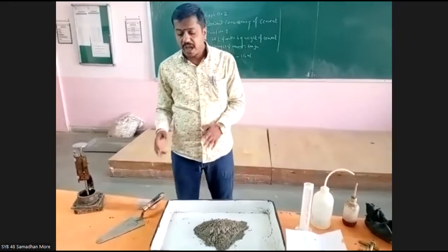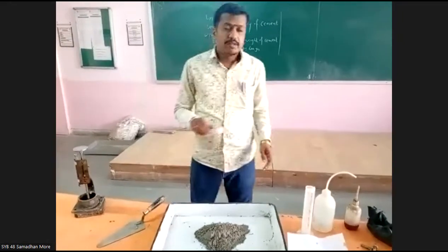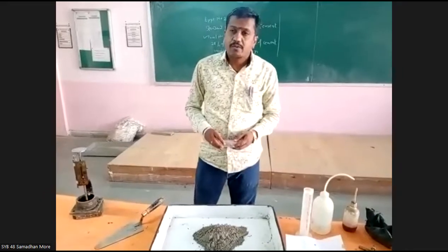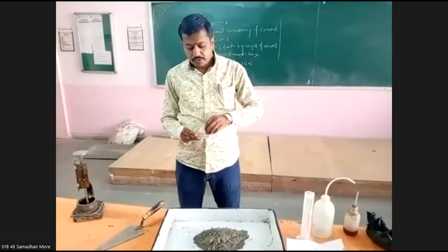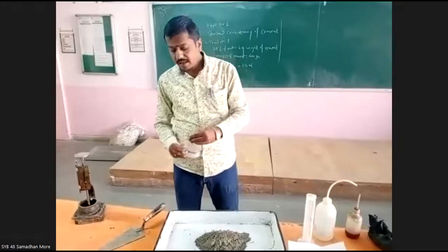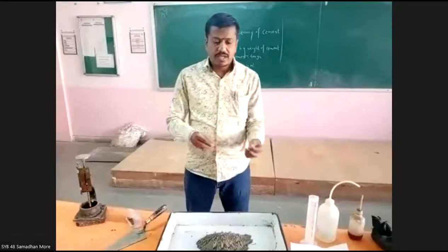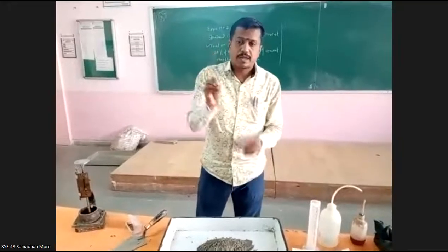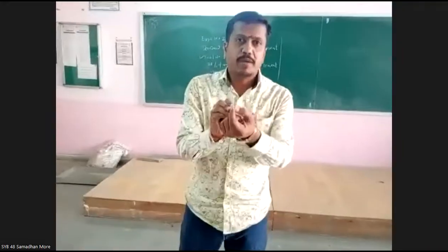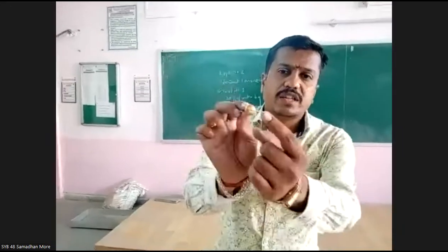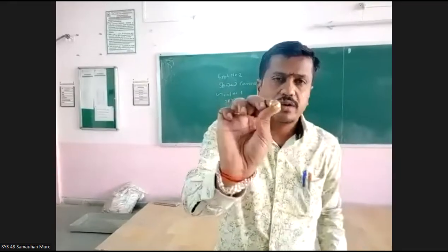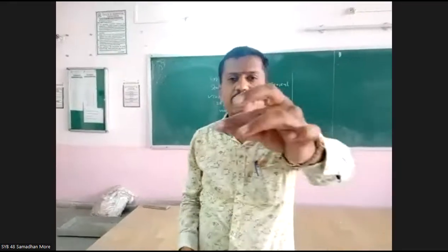And in the second half, we are going to take again 400 gram of cement and we are going to use 2 needles to find out the setting time. The 2 needles are initial setting time needles. As you can see, this is the first initial setting time needle. Okay, the area of this needle is 1 mm square. You can see this is the initial setting time needle. The area of this needle is 1 mm square. Okay, 1 mm square.